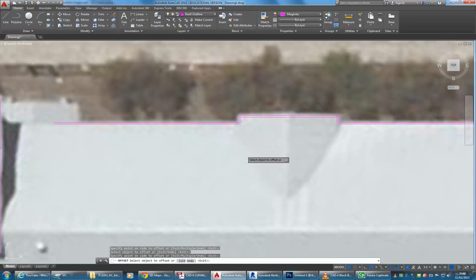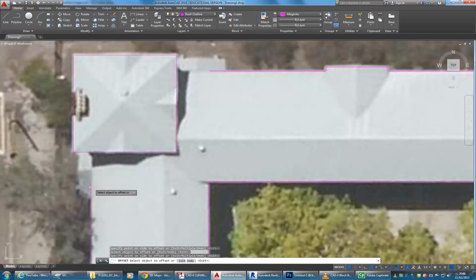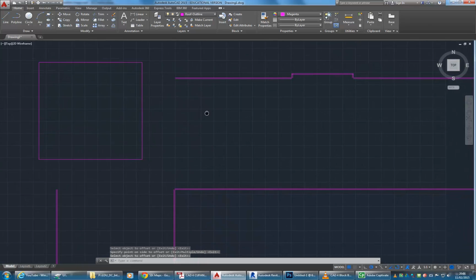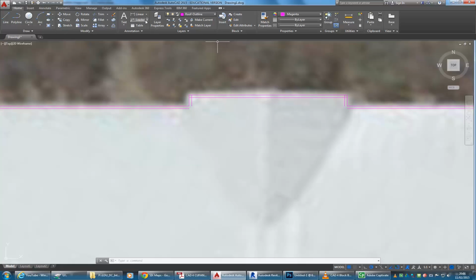100 mil. And then you probably might know that if you make polylines, you don't have to join these. But I think that's making it too complicated. So I'm just offsetting the individual lines as they are. Yeah, inside. 100 mil. So would you do a midpoint on that each? Oh yeah, definitely. And so I'll fill up these together. So if you don't remember, enter repeats the last command, so you don't have to keep clicking on the button.